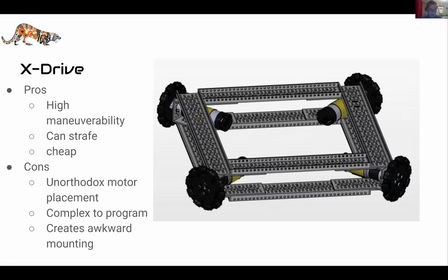The X-Drive is also decently similar to the Mecanum drive because it can strafe. It can pretty much go in all directions you want. It's a little bit cheaper because you don't have the Mecanum wheels. They're just omni wheels.